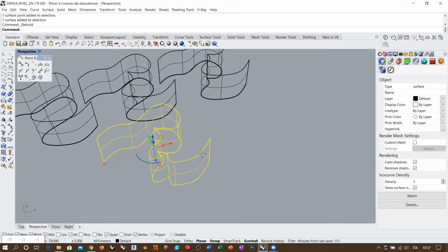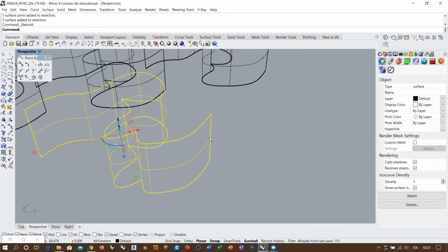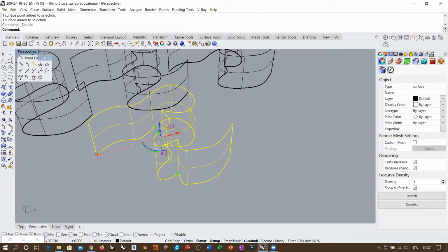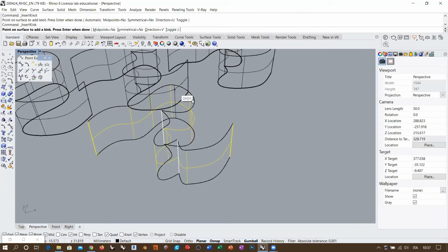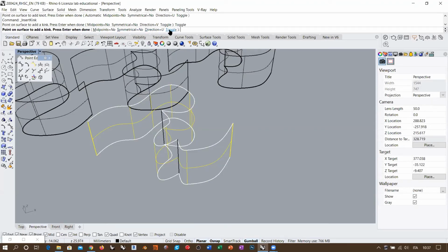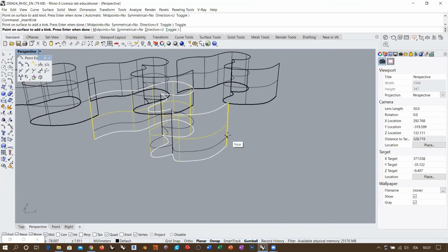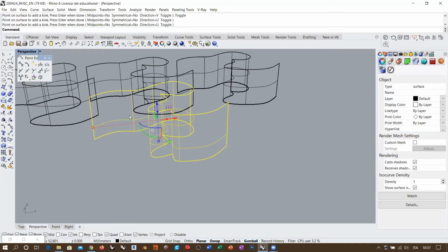So no internal control point, and therefore there is no internal knot. So this is a visual isocurve. It's not actually corresponding to a knot line, okay? But anyway, if I try to insert a kink along this line, not vertically, but toggle horizontally, and I do, for example, this and enter, now you see that the original isocurve has disappeared because it was only visual.